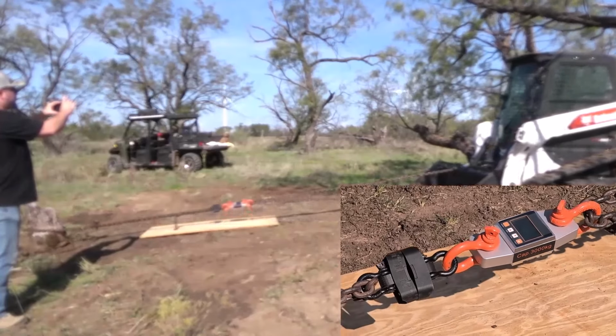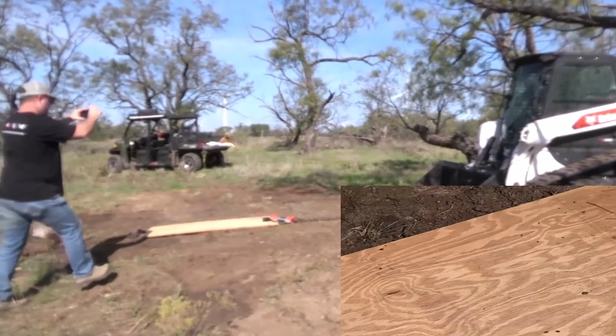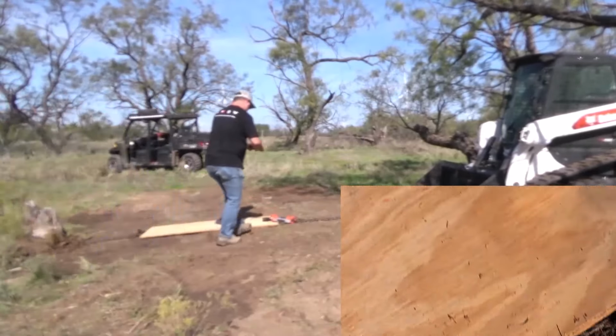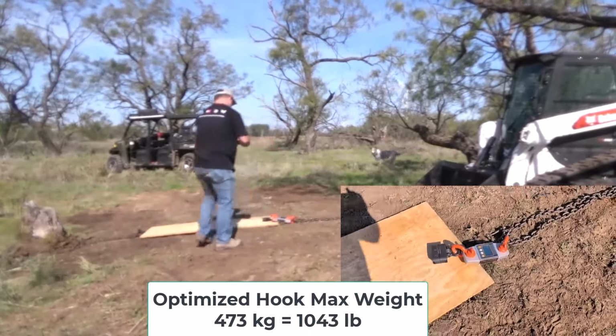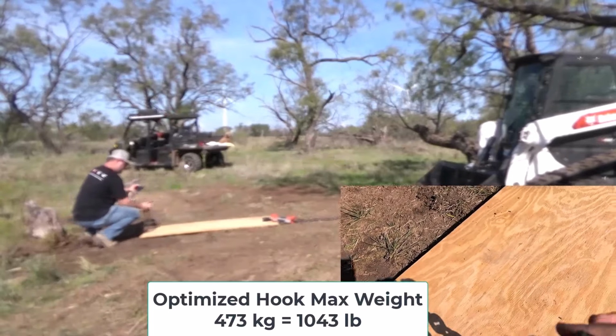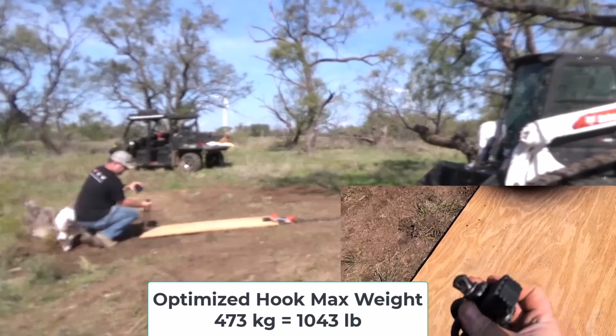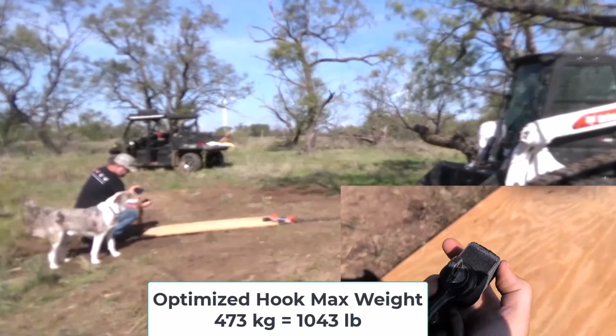Starting to pull, starting to separate, and now we have a break. 473 kilograms. Let's take a look and see what we lost here. So it looks like it broke in the sparse fill down here at the base of this hook.